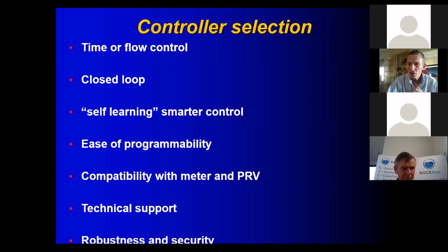It's important to realize every additional item that you add to your pressure reducing valve is an item that can break down or go wrong. It adds further complexity. So for every benefit you get, there is an associated disbenefit, either through maintenance and breakdowns. So it's always a balance trying to find appropriate technology.